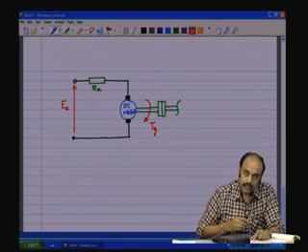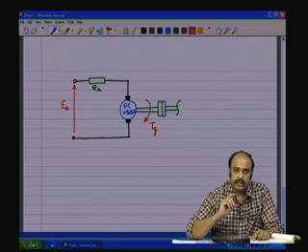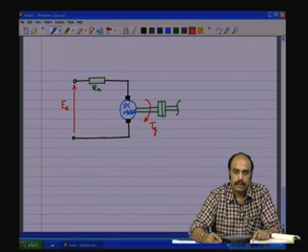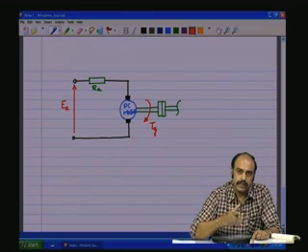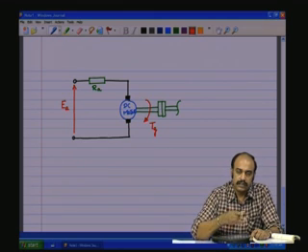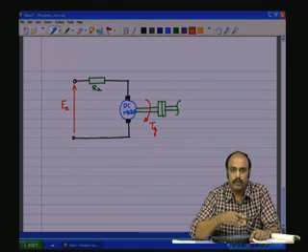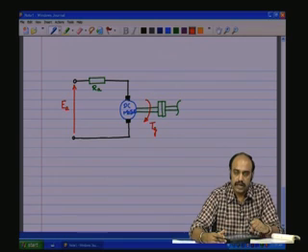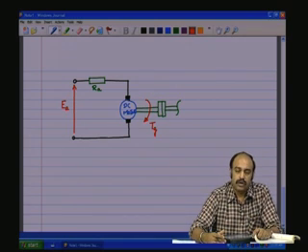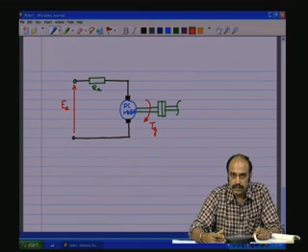Now, we saw that in the case of the DC generator, due to an external load connected, there was a load current I which was flowing, and the I got reflected back through the magnetic domain and then finally into the mechanical domain as a Lorentz force or the Lorentz torque, against which the prime mover had to force the torque, thereby giving the mechanical energy.